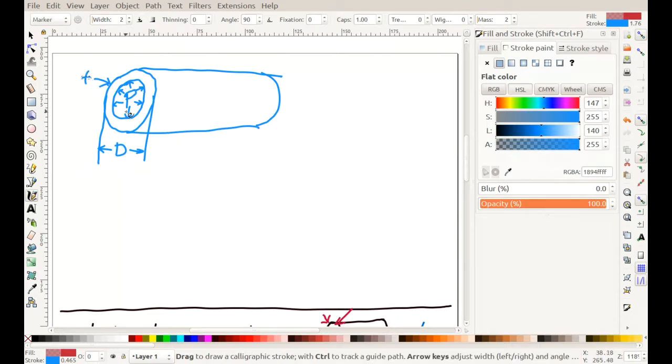And so knowing the pressure and knowing the area on which that pressure acts, we can come up with a force. So if I take a look at a shell, I can see that there are forces that are acting circumferentially, and there are forces that act longitudinally. Okay, and so this gives us two stresses.